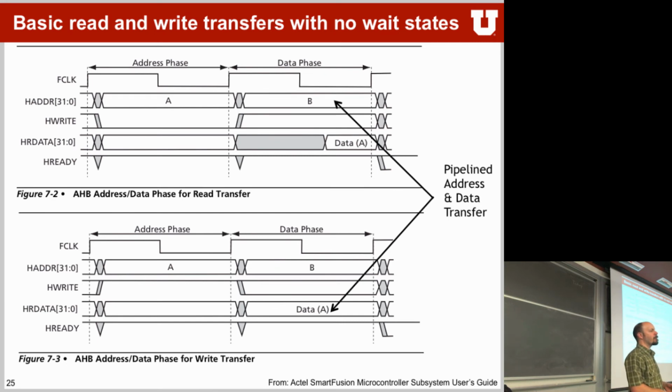Well, what would happen is the master wants to read from a location, and then the peripheral tells him, hey, wait, not so fast. Peripheral can't keep up with the master request. And when would that happen? How could this happen? An ADC. If you have to read a peripheral that's slow, right? In your case, you said an ADC, yes. Or if you, for example, have to read out of flash memory, the flash memory is not fast enough sometimes. It cannot keep up with the speed of your bus. So what the peripheral has to do is it has to wait for a couple of clock ticks until the data has been read out of your flash memory and put back onto the bus.